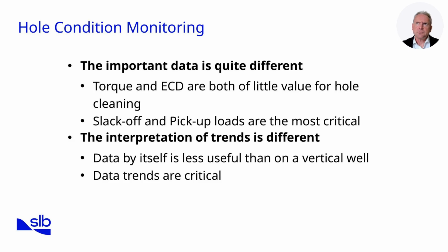In extended reach wells, the data we rely on to judge hole condition is very different from conventional drilling. Torque and ECD, while useful, are actually poor indicators of hole cleaning efficiency in long horizontals. Instead, the most critical values to watch are slack-off and pick-up loads, which tell us how much drag is building up in the string. The interpretation of these trends is far more important than the raw values.